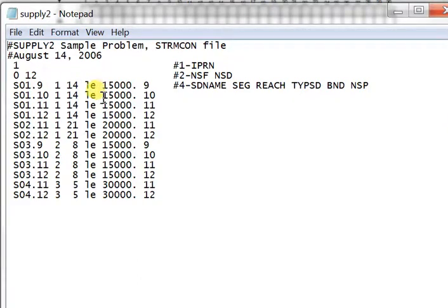This implies that there needs to be a base reference run where non-pumping conditions are determined, and those conditions can then be compared to the conditions computed under the optimal pumping rates to confirm that in fact we meet the constraints.